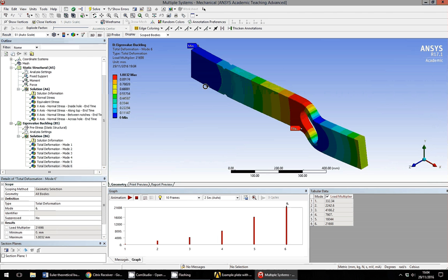That is a summary, in a simple case, of how to move from a static structural analysis to an eigenvalue buckling analysis. It can take a more complex structure and more complex loads, and it'll factor up all the loads linearly to produce a vector to see parts of the structure buckling. It will do torsional buckling, lateral torsional buckling, overall Euler buckling, as we've seen here. So local and global buckling of members is picked up by the model. So it's quite sophisticated.